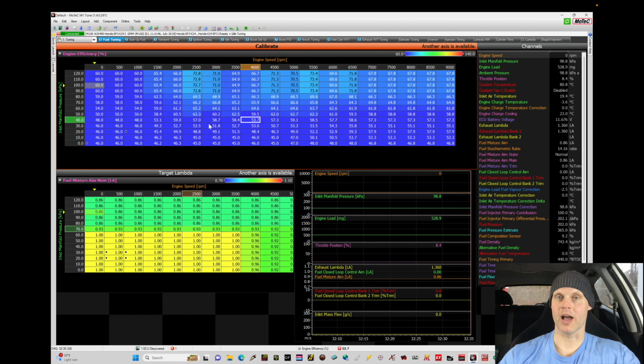Now we've mapped out in the last training module in pretty painstaking detail all of the things that are going to be making sure that the low cam was properly dialed in. So low cam is VTEC off, high cam is with VTEC on. So we have our fuel, our VE airflow models dialed in, we have our spark timing, we have our knock control centered around the engine and set up properly so that if it does start to get knock, it starts to retard the timing. We saw that in that last training module. And the variable cam control was optimized to give us the broadest torque curve possible on low cam.